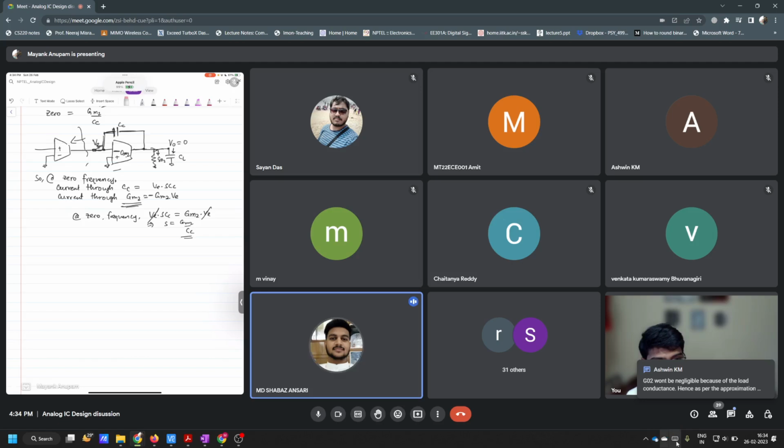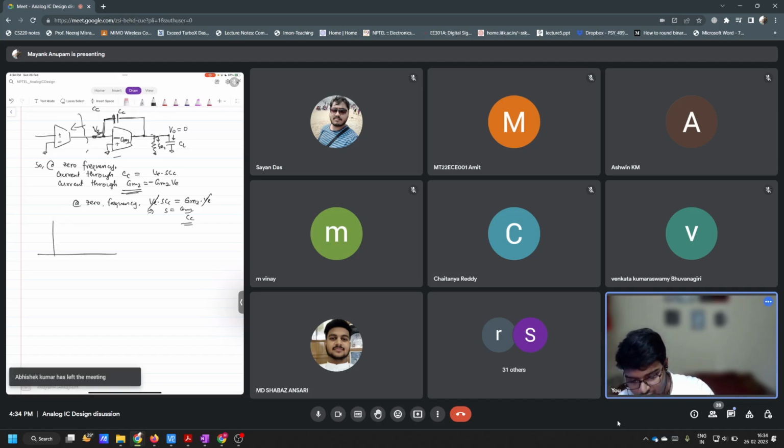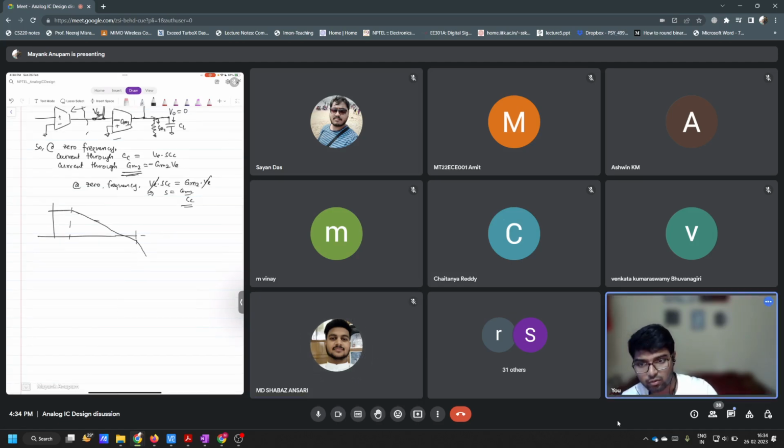So then, how do we get the new omega u loop when we consider the k gain? No, the omega u loop will be simply omega u over k, right? Let's say this was your loop gain earlier. You have pole P1, then you have pole P2 here. Now if you increase k, that means your loop gain will decrease.